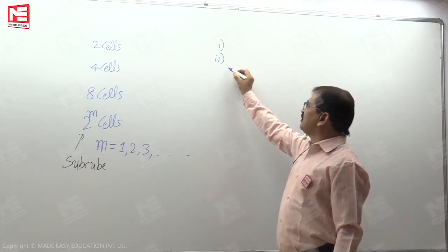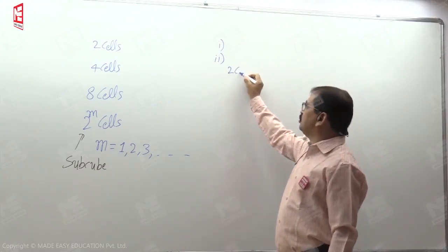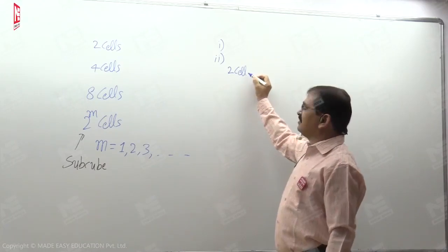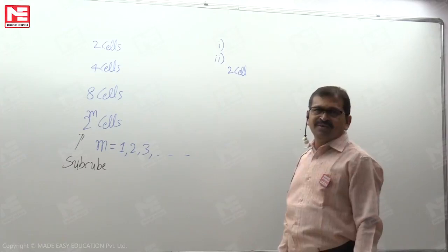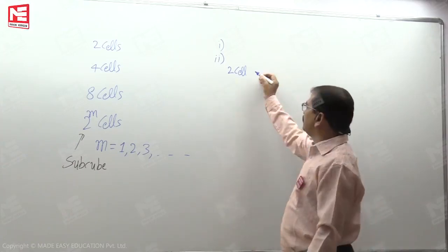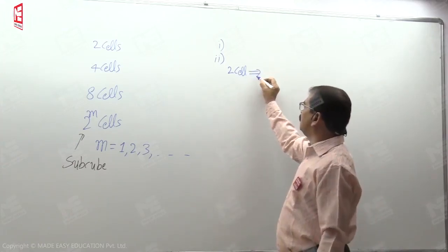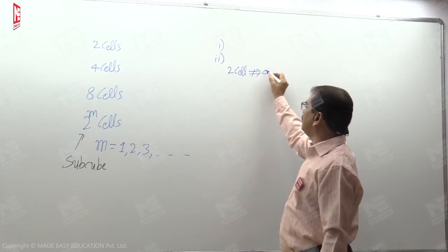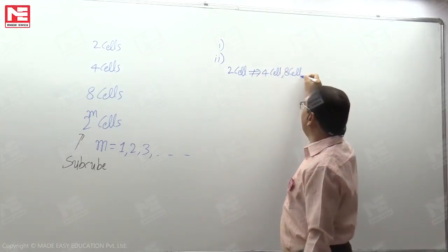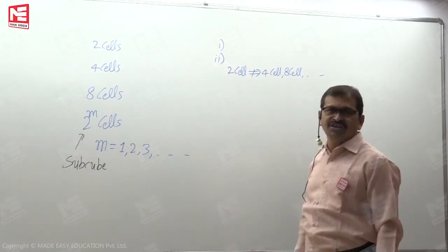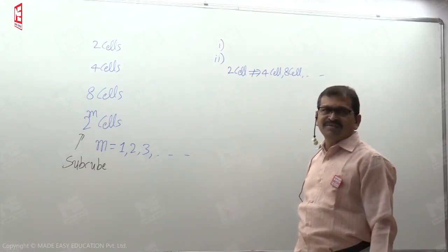So what we are saying is, mark all possible two-cell subcubes such that they should not be part of any larger size subcube. The meaning is, whenever we are marking a two-cell subcube, we need to take care that it should not come as part of a 4-cell or 8-cell or, in general, any larger size subcube.